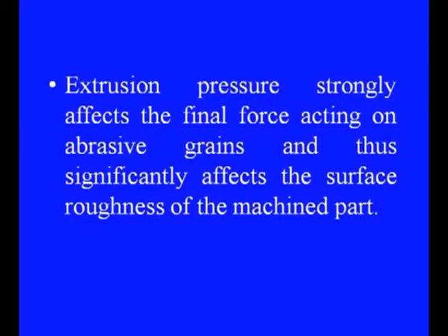Extrusion pressure strongly affects the final force acting on abrasive grains and thus significantly affects the surface roughness of the machined part. It was found that extrusion pressure affects up to a critical pressure point, beyond which even if the extrusion pressure increases, the surface quality does not get any better. Therefore, optimizing these process parameters is very important in getting a desired surface quality.